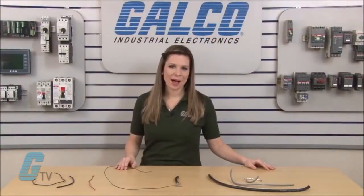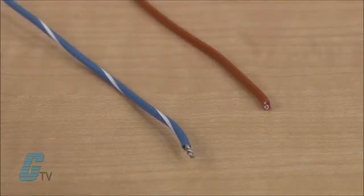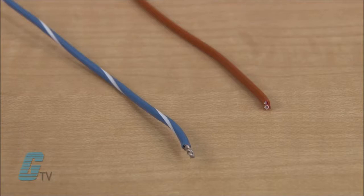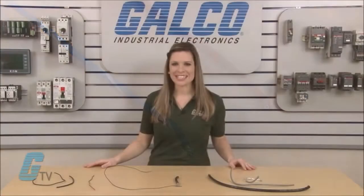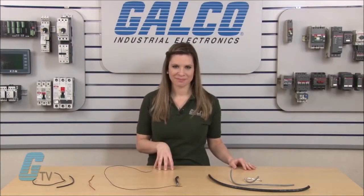The insulation and the outer jacket of the cable and wires is also an important factor. The types of materials used are usually a thermoplastic or thermoset. A thermoplastic material can soften under heat, while the thermoset material could vulcanize when exposed to heat and pressure. The insulation material may also offer a difference of protection.